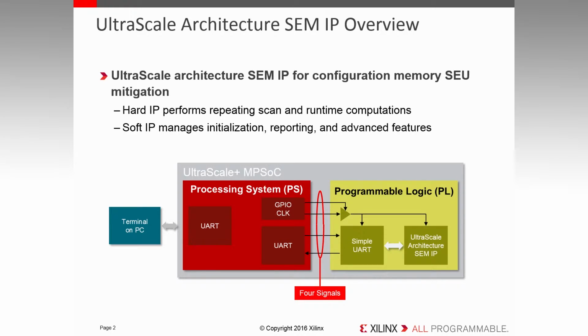Xilinx provides a complete SEU solution for UltraScale Plus FPGAs and UltraScale Plus MPSoCs. The SEU advantage of UltraScale Plus devices reduces total cost of ownership by providing reliability, availability, and serviceability. High reliability is achieved with ultra-low SEU rates through device architecture, circuit design, and process innovation. High availability is achieved with rapid error detection and mitigation responses. High serviceability is provided through detailed event reporting and runtime event assessment.